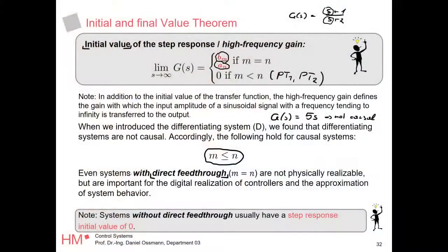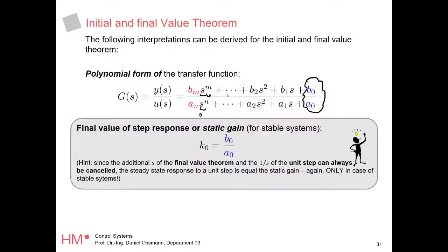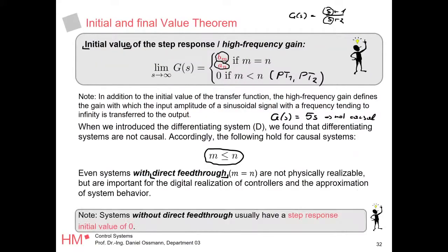Bottom line here is really the takeaway for you: look at the highest degree and you immediately know, look at the parameters before the highest degree and you immediately know the initial value of your system to a step response. Well, please always refer to a step response, right?